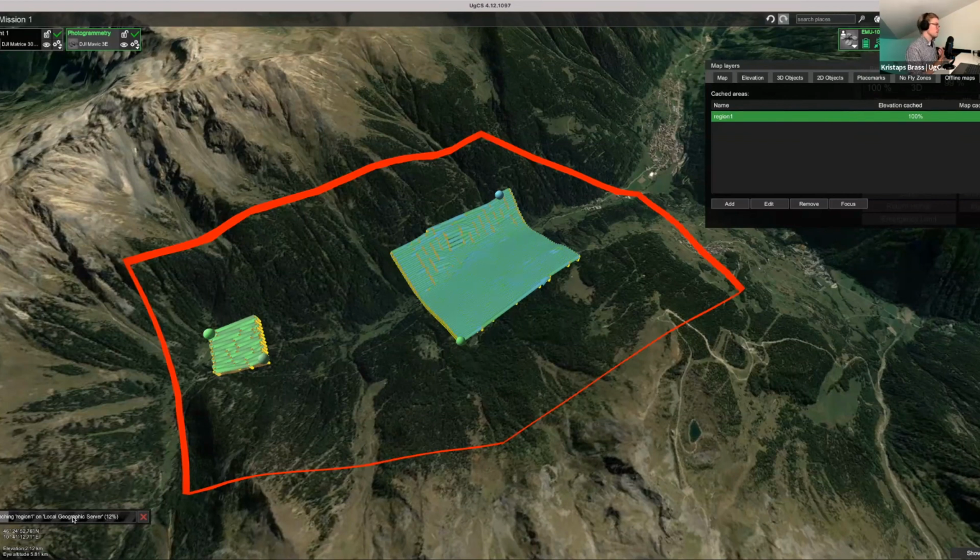Also, of course, good pilot skills are quite important. So in that case, make sure you're always monitoring the FPV camera if your drone is equipped with one. And if you see any obstacle that's getting a bit too close to the drone, take over manual control. That's always, of course, safer. I think the obstacle detection should only serve as a last resort. If all else fails, then you just cross fingers and hope that the drone will be able to stop in time. But again, this depends on the speed of the drone.